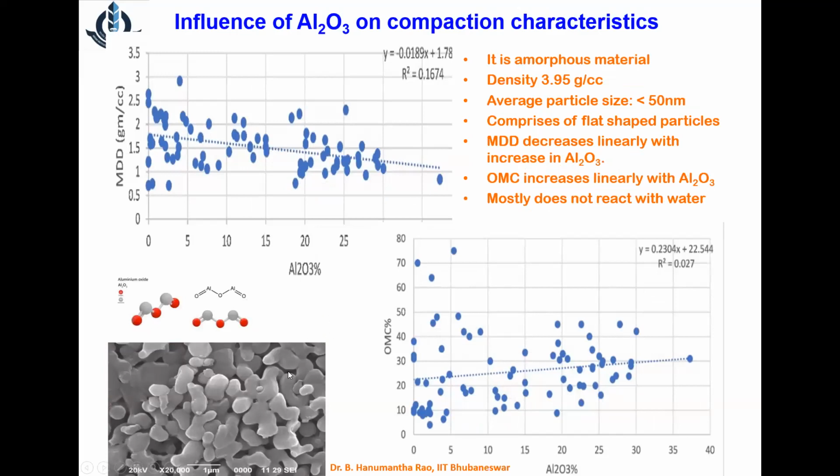Now you try to understand. Al2O3 is a platy particle, SiO2 is a spherical particle. Would they behave in a similar way when I do the standard Proctor or the modified Proctor? The question is, suppose a waste dominant with Al2O3 is used in the real field, and the same for a waste dominant with SiO2 in real field application, would they behave in a similar way under roller compaction? Someone may ask you the answer to this question.